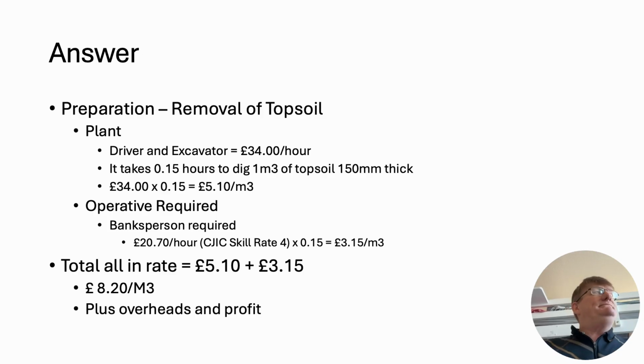Although the driver is labour, I appreciate that, he would be priced up within the plant section because an excavator or even a lorry, some big elements of plant which require a driver or an operator, would be priced in with those big pieces of plant. Okay, so a driver and excavator, I've just taken this off the top of my head, but you can look at it and find it from the internet how much they cost. So I said it costs £34 an hour.